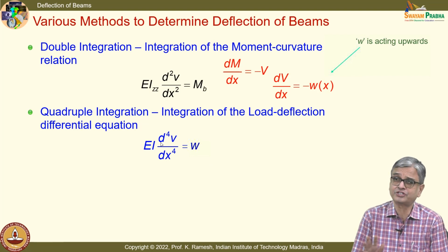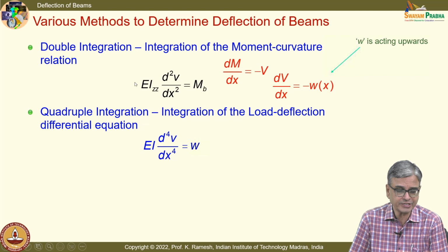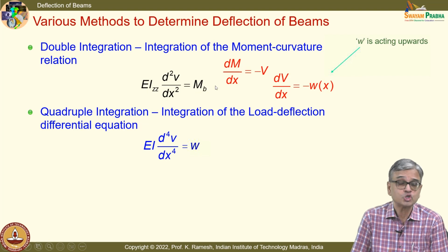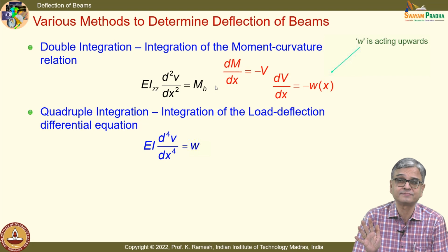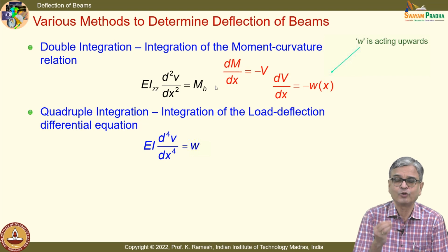It has an advantage. If you look at this expression, when you want to do double integration, I need to calculate the bending moment. So far, you have handled only statically determinate problems. I have also shown what statically indeterminate problems are, wherein you have to bring in what happens to the deflection. Only when you bring in the deformation do I get additional information for me to solve.